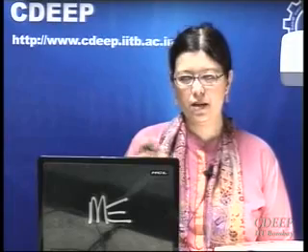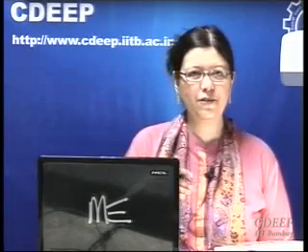The reason is early stages are very important. Every stage has a gain of 2. Therefore, your noise will get divided by 2. If you go from one stage to the previous stage, your noise will be divided by the gain of 2, and power-wise, it will be divided by 4. Therefore, the first stage is a very important stage with respect to noise.